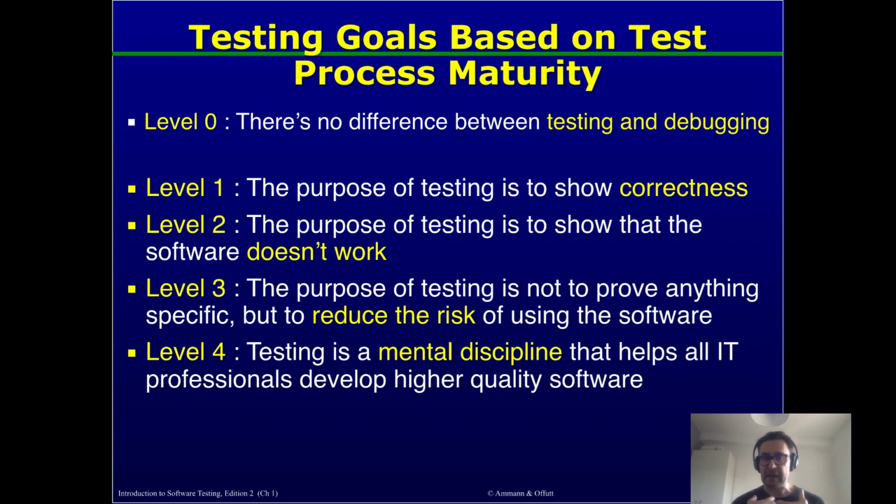So you don't have infinite resources. When you're building a bridge, you have to trade off how strong you make it compared to what the most likely use scenarios are. And then you often take a security margin. So you take, let's say, double or 5 times as strong as you think the expected load is going to be. So you're trying to reduce the risk, but you will not have the resources to make it 50 times stronger than it needs to be, right? So there are always going to be these trade-offs in mature engineering processes.